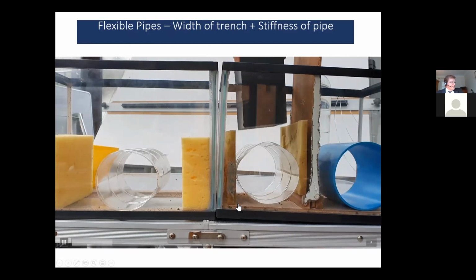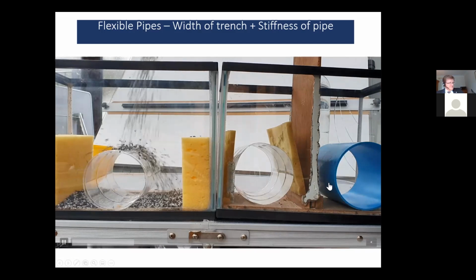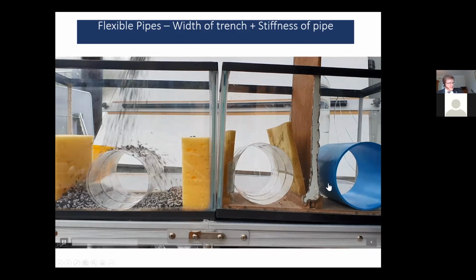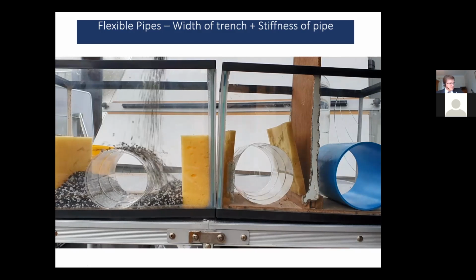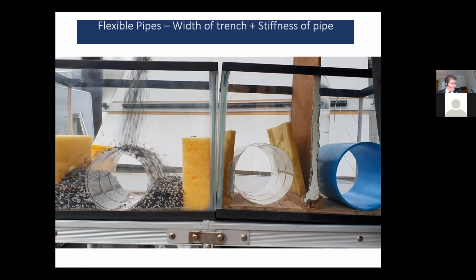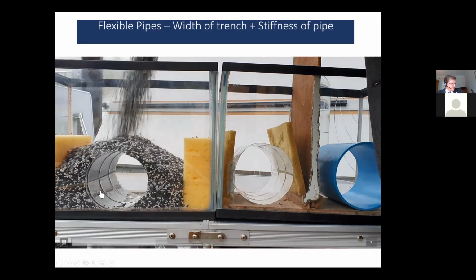There you go, that's the material. And we're then going to look at the pipe at the end, which is simply a stiffer, flexible pipe, and the difference that going for a stiffer pipe makes. So there we go, nice class S1 material. As you see, the pipe trying to move around as the material is poured. Material running beautifully and compacting underneath the pipe, which single-sized gravels do.